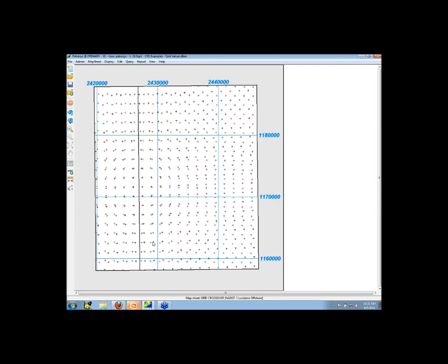My blue lines are representing the Louisiana offshore tick marks, or the Louisiana offshore coordinates, and here are my red grid nodes, and then the black grid nodes. So it's two overlapping grids in this area, and we can see that these lines are not perfectly straight anymore, and it's because Petrosys is reprojecting those coordinates, and they're being a little bit distorted, so they don't form these perfect straight lines anymore, so that everything's being displayed accurately on my new projection system.